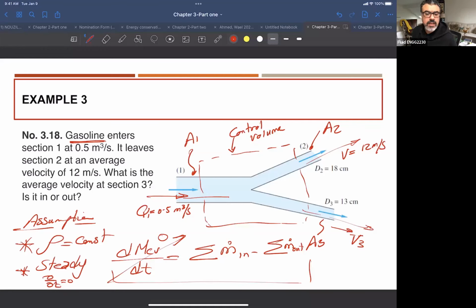You don't see any option here for the fluid to be compressed inside this control volume. Whatever coming in is going out. So within the system, there is no variation inside this control volume, right? So it is a very valid assumption here. It's almost like a junction box. What is coming in is just going out, no accumulation inside, and no mass change of the system.